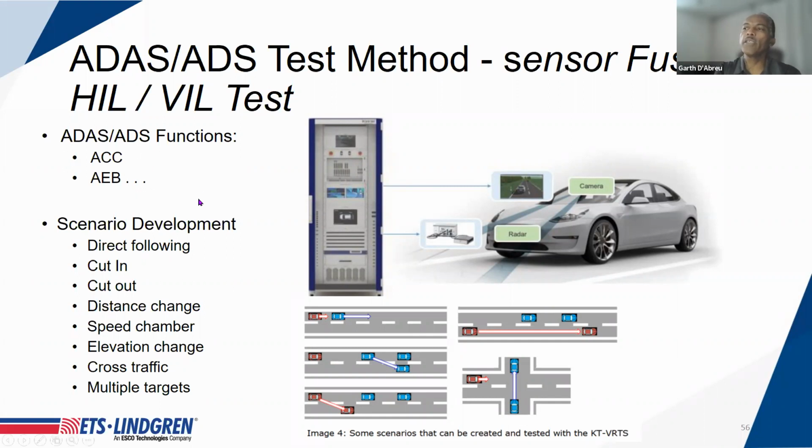And the intent here is to really create an environment where you can simulate a target vehicle positioned in front of your vehicle's radar module. You can adjust the distance, the cross-sectional area of the target vehicle, and its speed, the Doppler of the vehicle, so that you have flexibility in where and how that target responds.